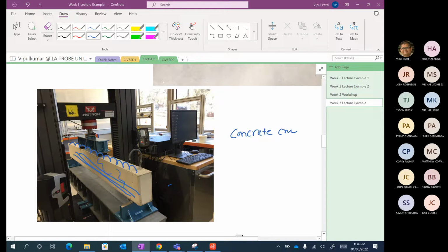So if the concrete starts cracking before the steel yields, then if I am sitting here under your beam, all the concrete will fall on my head and your steel bar is sitting there doing nothing. So we make sure that the steel will yield first, the steel is going to bend and hold the concrete. The concrete will not just brittly snap. So we make sure that the steel bends, yields, and then the concrete will start cracking.